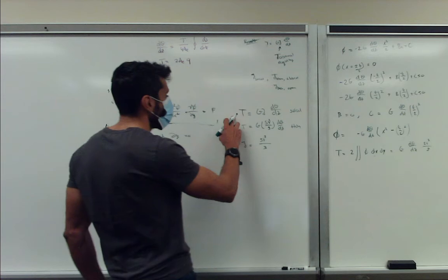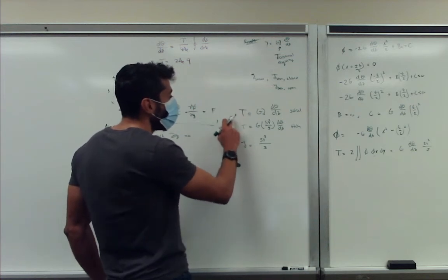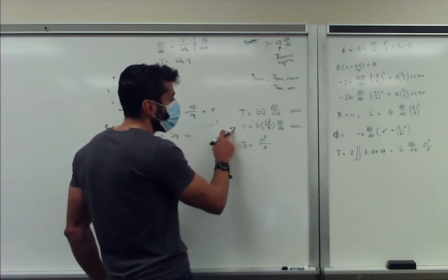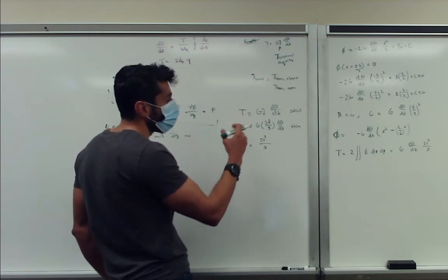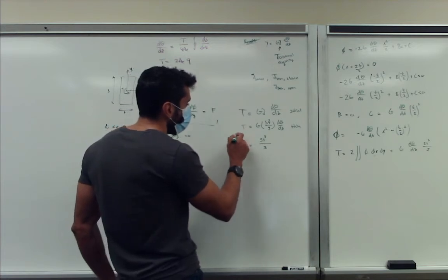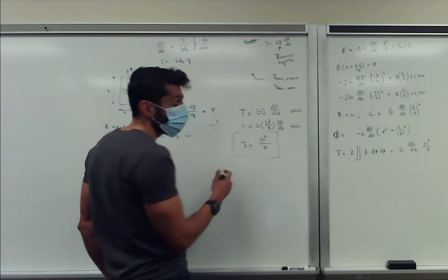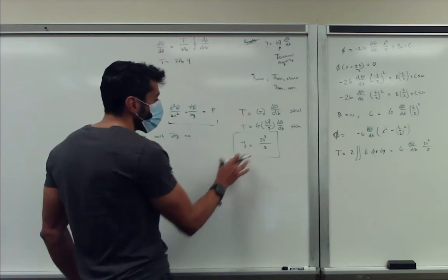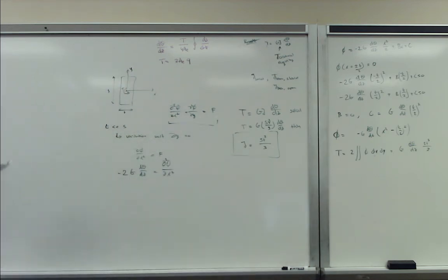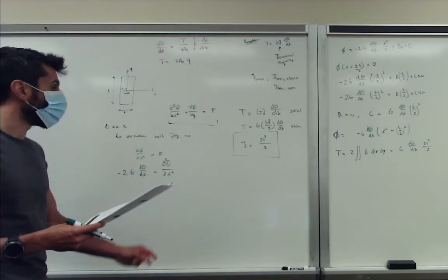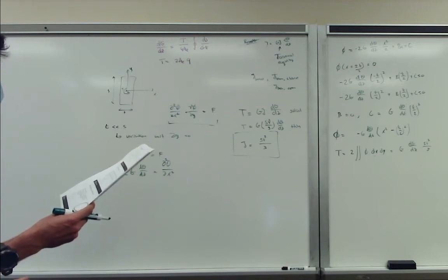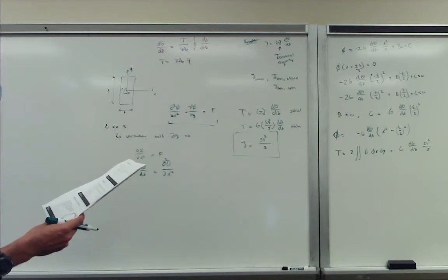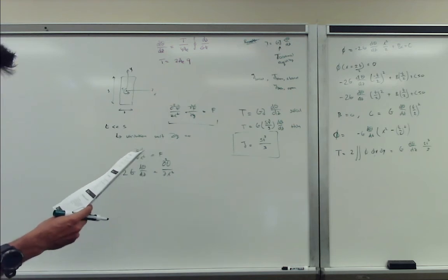Since we start with the same formulation, we compare our solid section with what we newly derived for the thin-walled section, aka the narrow strip, and we realize that for those two to be equal, J must be equal to S times T cubed over 3. So this is valid for long rectangular sections, aka thin walls.